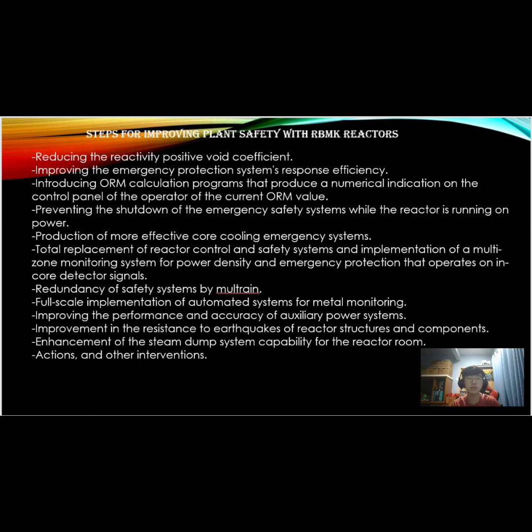Fifth, production of a more effective core cooling emergency system. Sixth, total replacement of reactor control and safety systems and implementation of a multi-zone monitoring system for power density and emergency protection that operates on in-core detector signals. Besides that, redundancy of safety systems by multi-train.